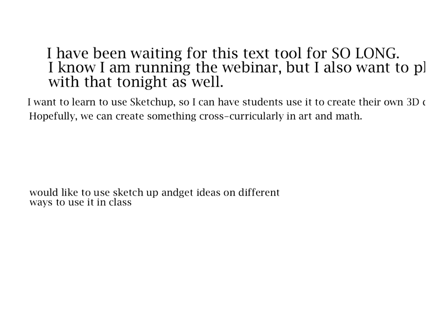Where SketchUp has kind of an easier learning curve is you can actually draw with straight lines. So instead of having to grab that primitive and then stretch it into position, I can just sketch a bunch of lines on the screen, and then I use something called a push-pull button in order to turn that thing into a 3D shape. So it means that the types of shapes that you can create are a lot more complex, and it means that when you're making changes to those shapes, you can do things like slicing off pieces of them.